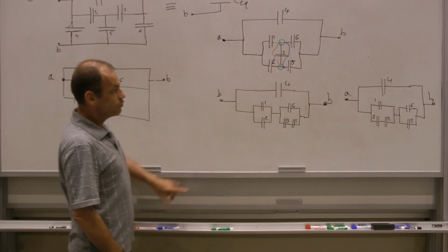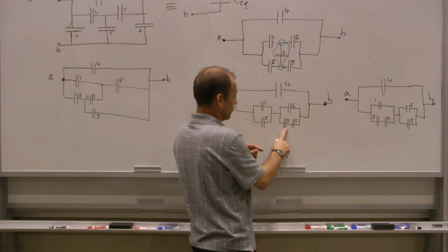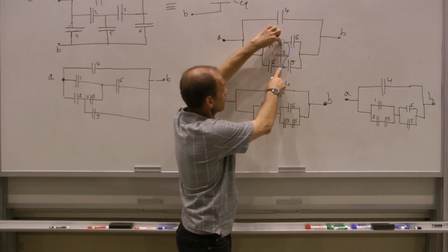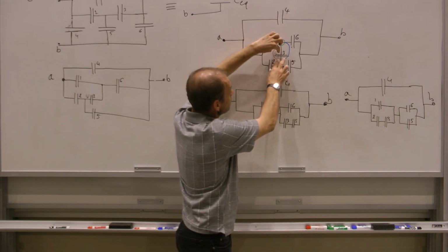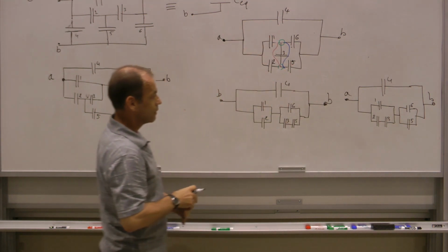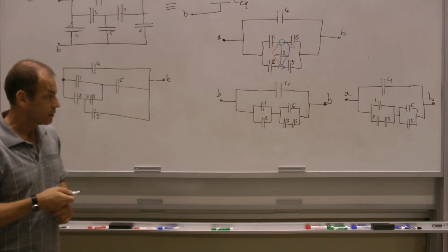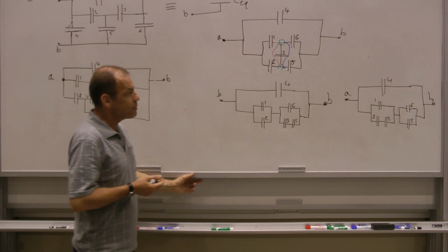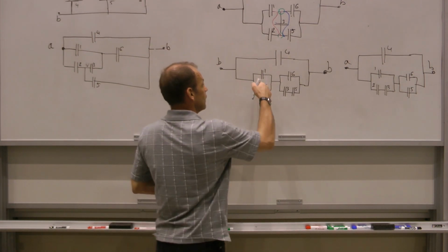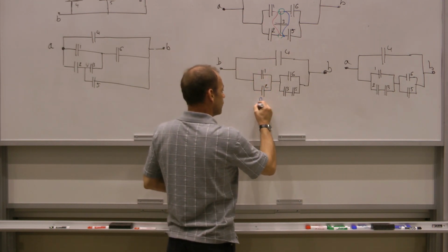Wow. These two configurations are exactly the same, we just, depending on where you put capacitor 3, because again, these two nodes are equivalent to each other. So I can combine 3 with 2 or 3 with 5 in the lower portion of that circuit. And this is of course because the capacitors are equal to each other. So now it's just a matter of regrouping everything. Say I work on this one. This one I have, each capacitor has a capacitance of C, they're in parallel, so they double up. I have 2C right there.